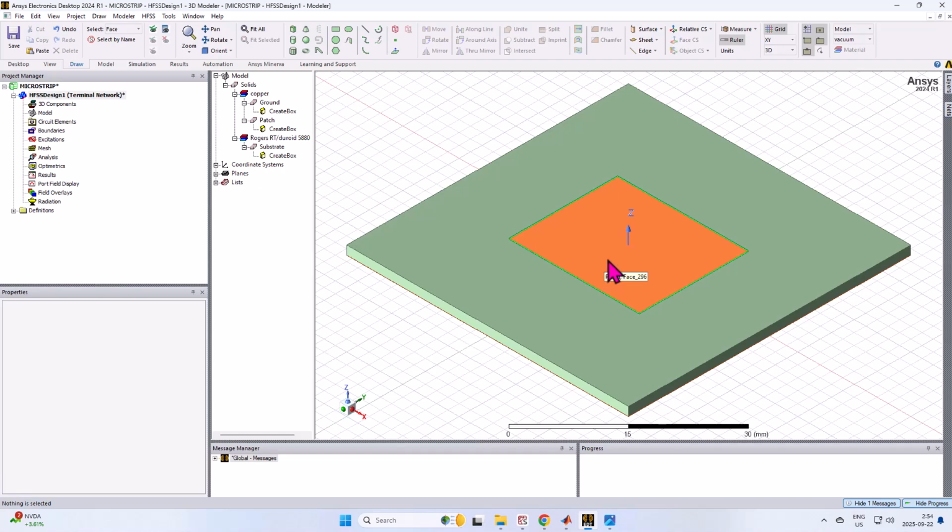I don't want to say exactly 50 ohm, but it will be close to 50 ohm. Practically this is true, but if you wanted to make it better, you can optimize it. So I just wanted to add the trace and cut here about 1/3 of that, and then add it. I will show you in a couple of minutes.